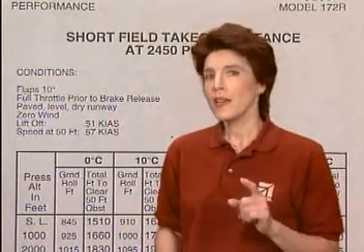So does this mean you shouldn't use this chart? Well, goodness no, it can be an excellent confidence builder and even a decision helper. For instance, you might find yourself at an unfamiliar airport and you're not sure how well you or your Skyhawk will fare. Just perform the short field calculations, and if the available distances are about 50% greater than what you calculated, you can depart and not give it another thought. If, on the other hand, the available distances are only 25% or so better than your calculations, you should probably do something to stack the deck in your favor.